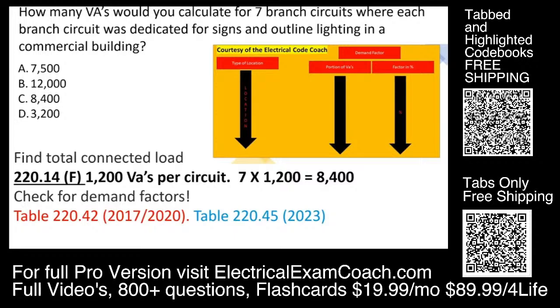And when we get there, we're going to start on the left-hand side of this table, and we're going to look for our type of occupancy. It does not mention a generic commercial building. It only mentions dwelling units, hotels and motels, so on and so forth. So if your area is not listed, you have to go down to the bottom to all locations not specified below. Then we cross over and find out that there is no demand factor when you're dealing with this type of lighting, and we're going to select C.